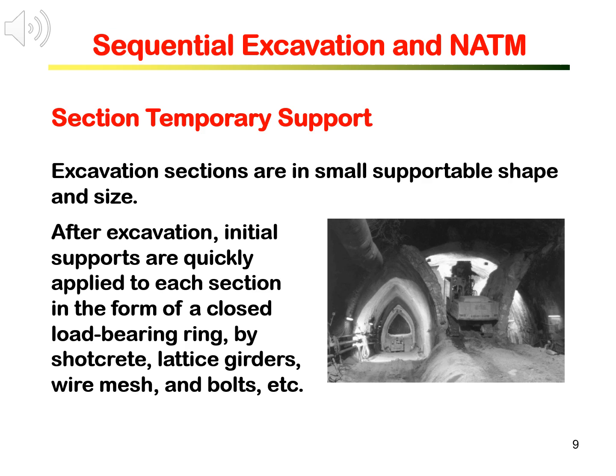Here you can see the excavation sections and the temporary support for those sections. The sections are in small, supportable shape and size. The supports are quickly applied to each section after excavation in the form of a closed load-bearing ring by shotcrete, reinforced by steel fiber, and perhaps with lattice girders and other support elements.